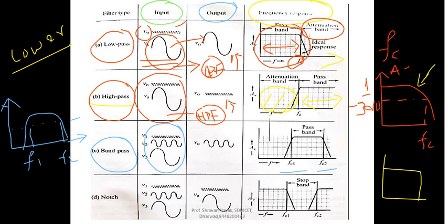One is Vs as usual, low frequency. Another is V1 here, right, or V3 we have taken here, V3 of low frequency, V1 of very high frequency, and V2 of the frequency between V1 and V3. And your output here will contain the signals corresponding to the range of V2, what you can see in the frequency response curve, right.